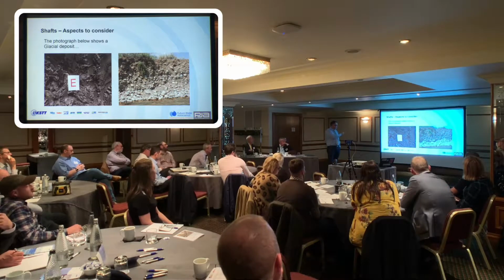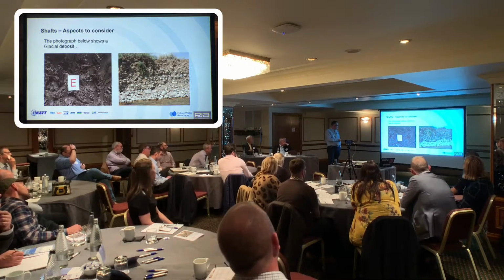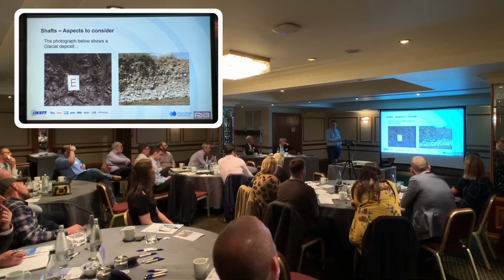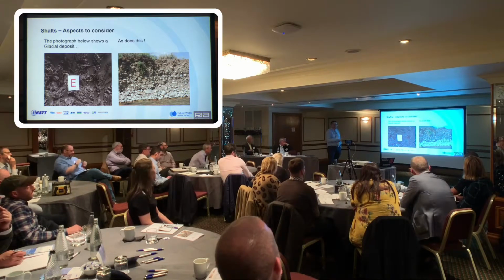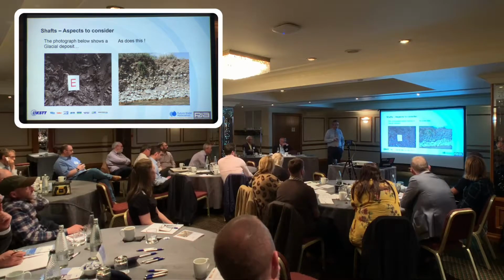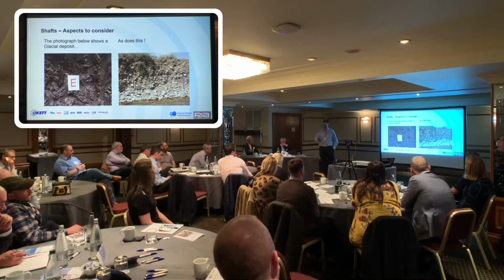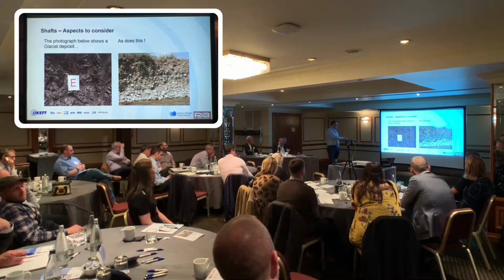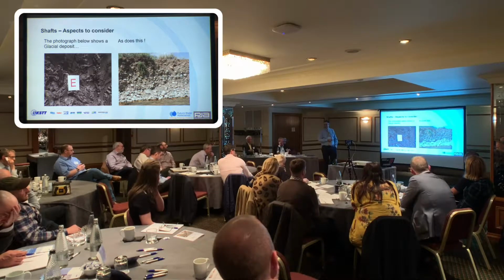On the left there, that's a glacial deposit. It looks like a decent enough clay, and you'd be quite happy going shaft sinking in that. But that's also a glacial deposit as well. That links back to what Dave was saying earlier about site investigation: it is important that you get someone to have a look who does understand what they're being told. If you just look at a borehole or a map and it says glacial deposit, and you've got that in your mind, that would be a much more challenging kind of terrain to drop a shaft in.